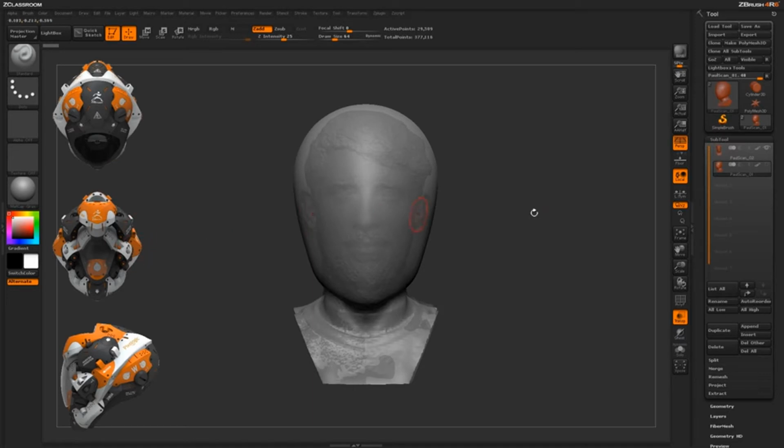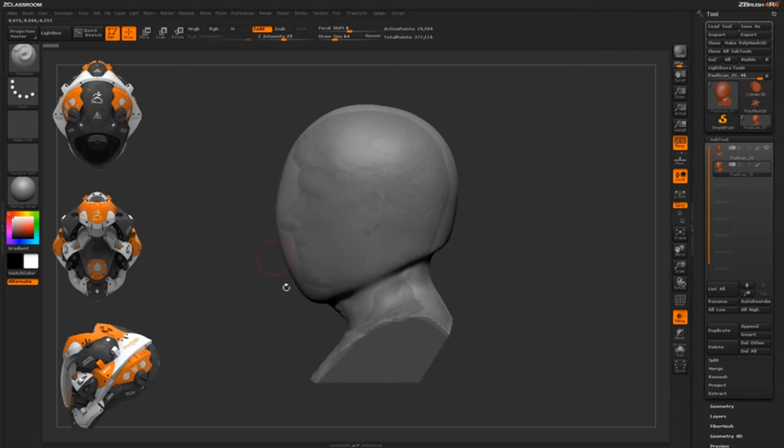When I'm actually building the helmet, I want to make sure that nothing goes inside of this structure, but all the helmet features come out of the structure. So I'm giving thickness outward instead of thickness inward. This gives me the base shape established for that interior part, so when this goes to be 3D printed, I'll have a nice cavity that Paul's head is going to be able to fit right inside.